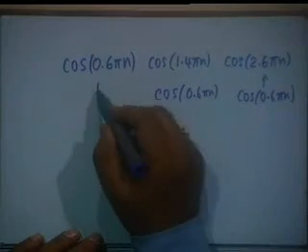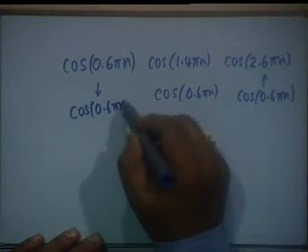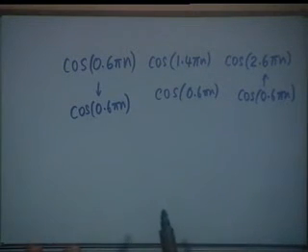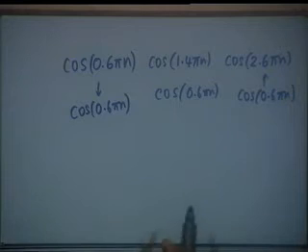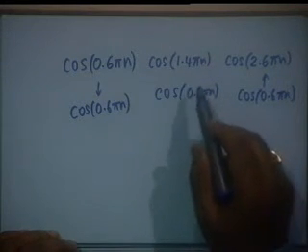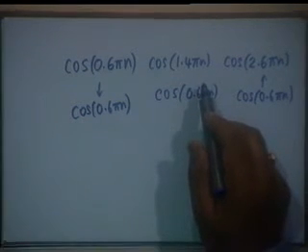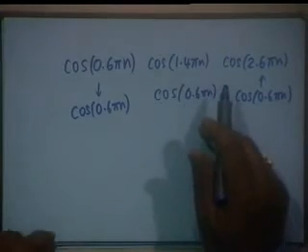In other words, the 3 signals become indistinguishable. This is what inadequate sampling frequency does. The 7 hertz signal now poses as if it is a 3 hertz signal. A high frequency poses as a low frequency.